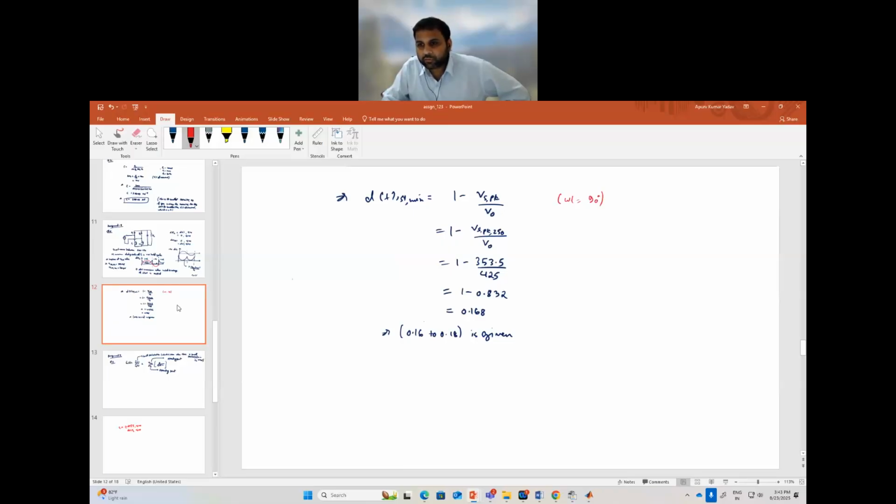Now there are two voltages which are given, because voltages are varying between 200 volt and 250 volt. Since we have been asked for the minimum value, we have to take the data for the 250 volt case, because that will give you the lowermost duty ratio. So that is the reason why we have taken 250 volt for Vs peak. Since it is given as 250 volt RMS, we have to convert it into the peak value, and that we will get over here.